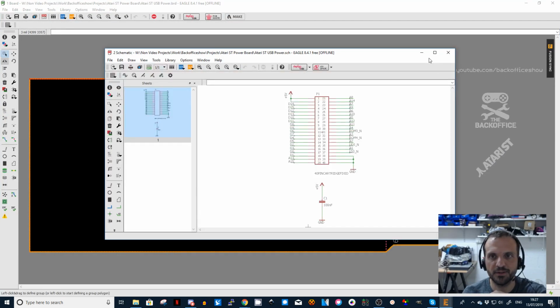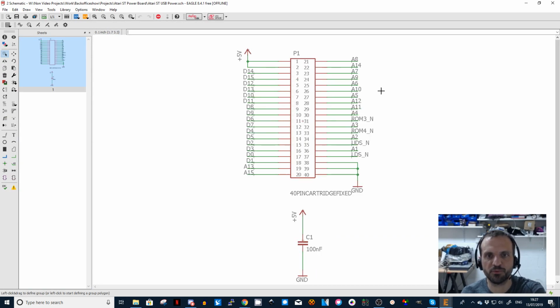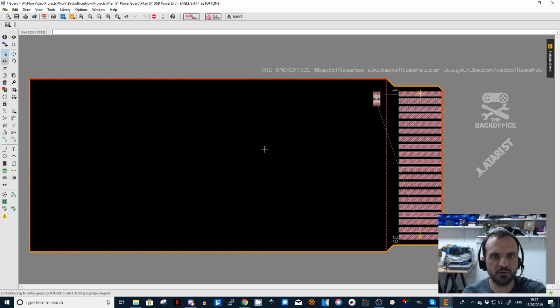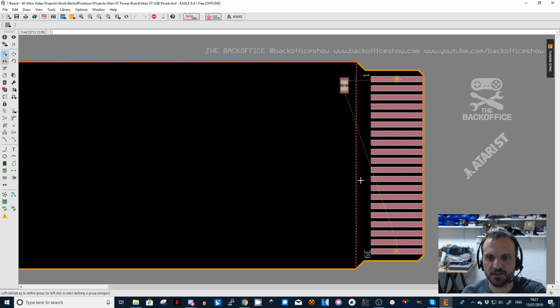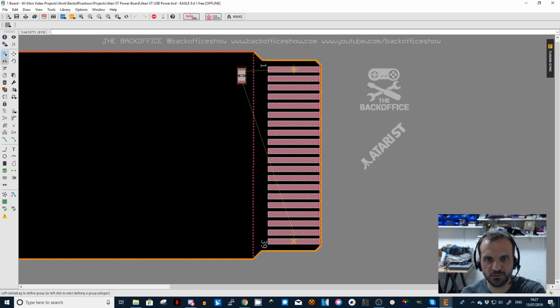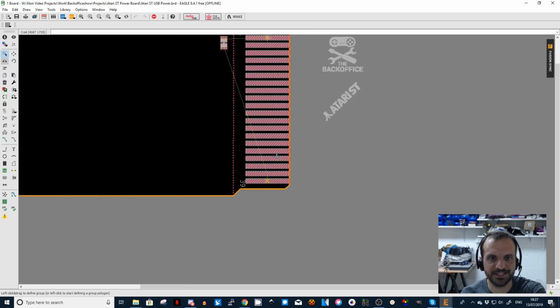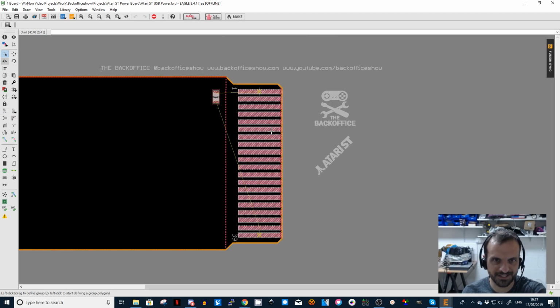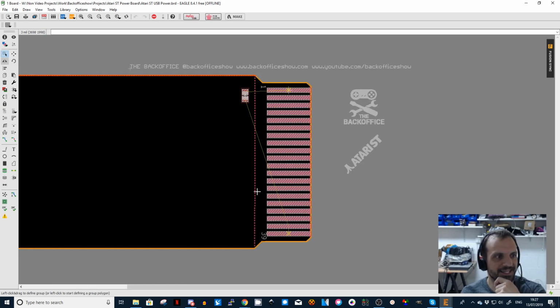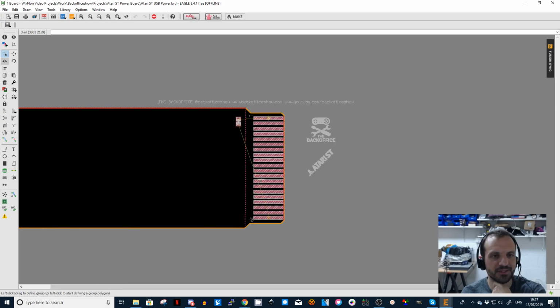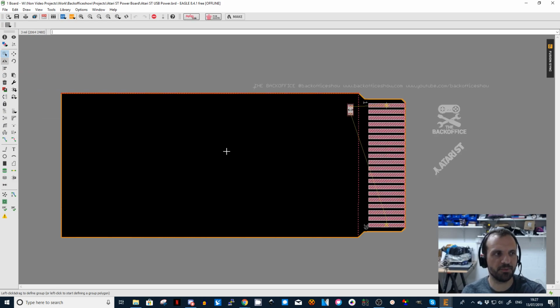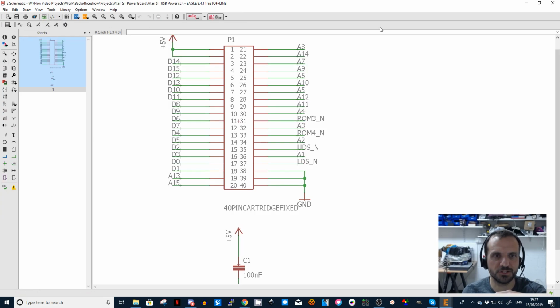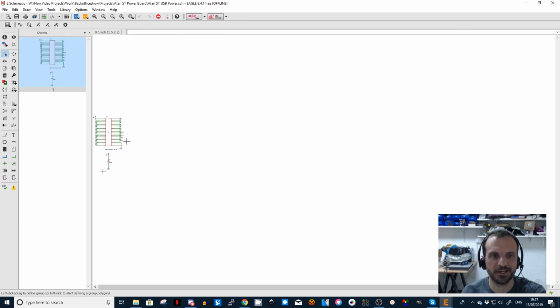And you'll see the pinouts for this footprint are pretty much the same, but when I go over here, you'll see now it's 1 to 39. Yeah, that makes a lot more sense because in the old one it's obviously 1 to like 20. It's 1 to 39 because it's staggered across them. Yeah, the OE and the CS. If you imagine the swapping of the OE and the CS, you're doing a double swap because you've got an issue where it's not quite right still.